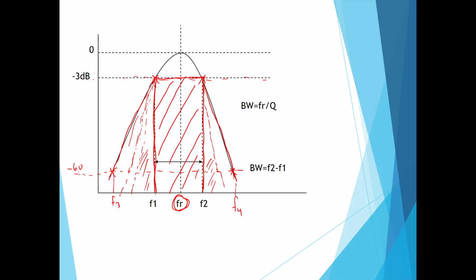Because the wider the slope, the wider the curve, we will capture many frequencies in the system. The wider the skirt, the more frequencies it will capture. So that means the steeper the slope is better. That means we want the filter to be able to move towards the ideal case, which is like this. So that's the issue of the filtering process.